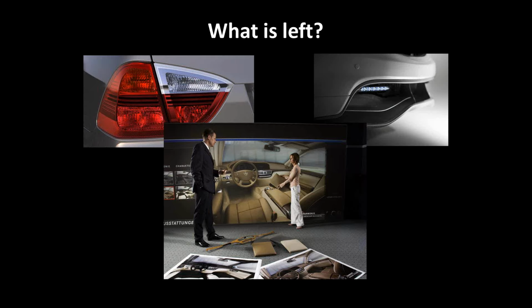or polygons, they have a problem because the stuff that I know from the NURBS work, trimming, is not possible there. So that means when I'm used to NURBS, and when I want to add a detail, I can just trim the surface, and the highlight picture and the structure of my underlying surface stays the same. But in polygon modeling, when the user wants to add a detail, he destroys the underlying surface and makes it smaller, it changes it a little bit, and so it's harder to do details, and it's harder to reach a certain level of details, you know, to show for the lights or even other things. And there is no discussion that probably some polygon models are good light models, and that's all okay, and I will never deny that. And in general, I think I'm okay with this.